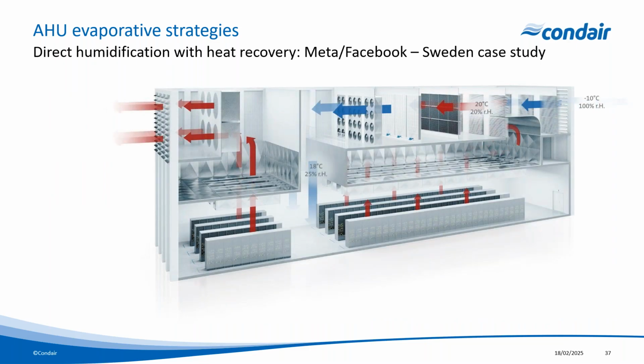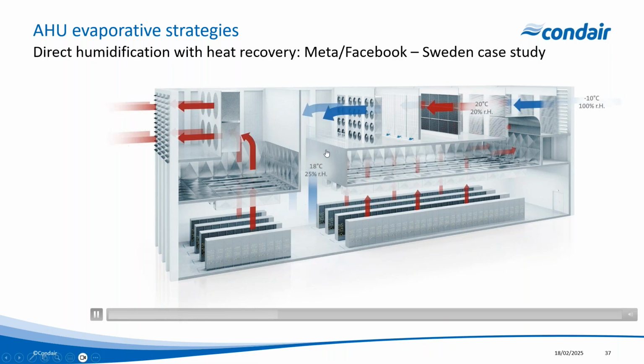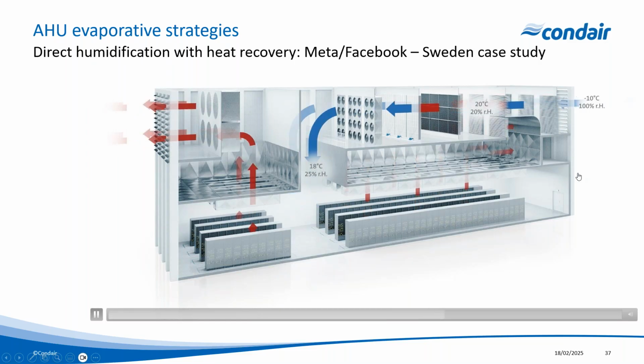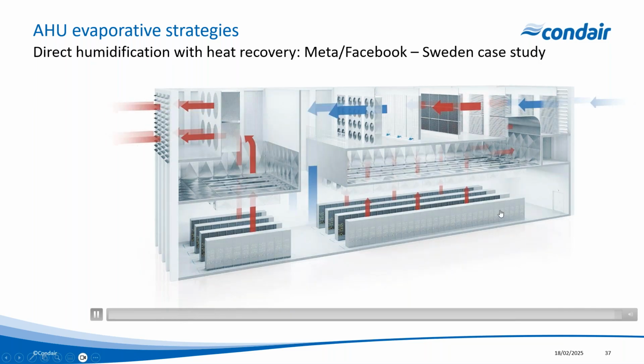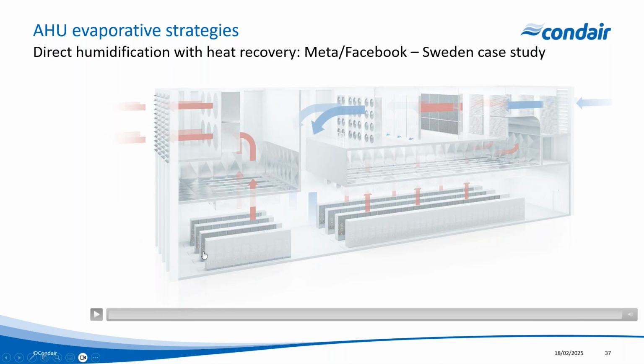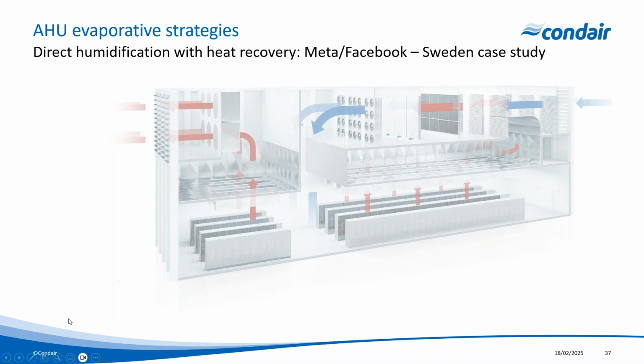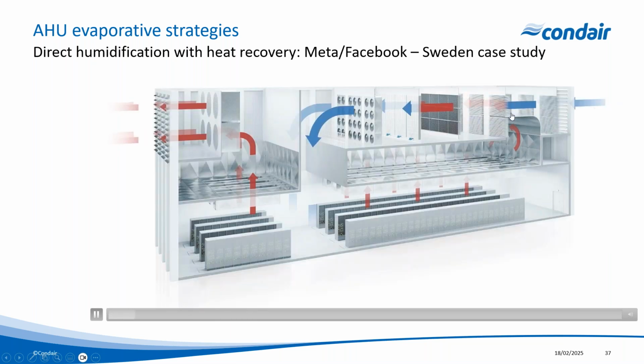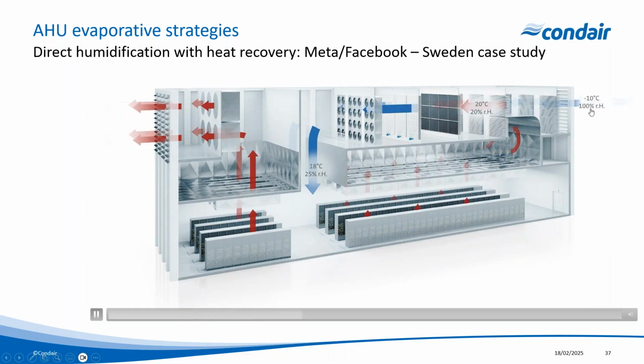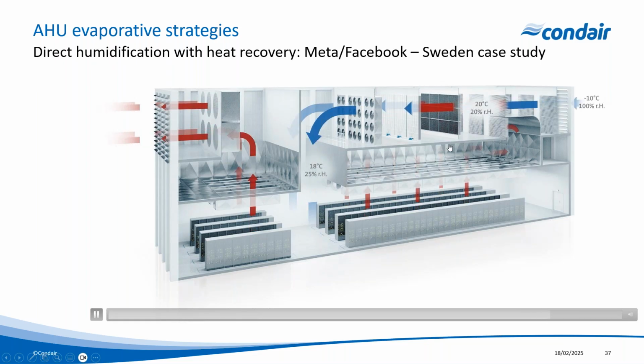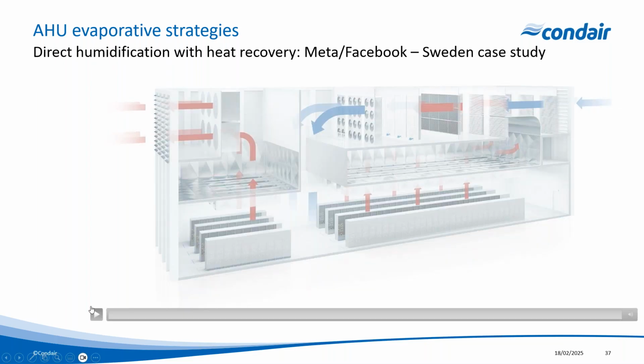So here we can see a schematic of the system, which in this project is referred to as a penthouse ventilation system. Each one is referred to as a lineup, and there's 13 lineups per data hall with 2 data halls in this building in particular. So one lineup consists of an intake plenum, return plenum, filters, humidifier, supply fans, relief fans, and then dedicated controls for each of those. As you can see on the right side, we've got cold outside air dampers, cold air coming through the dampers, bringing in fresh air. We have hot air coming back from the space where it's mixed in the mixing plenum with the cooler outside air. That mixed air then goes through a set of filters,